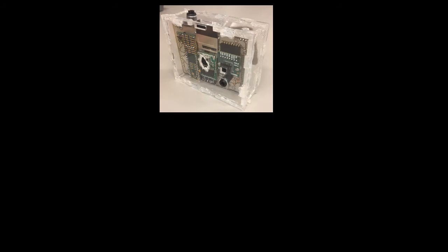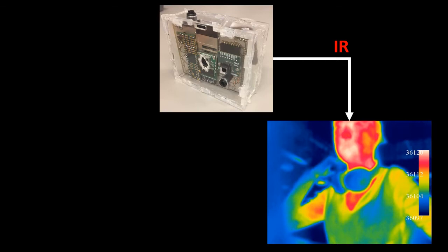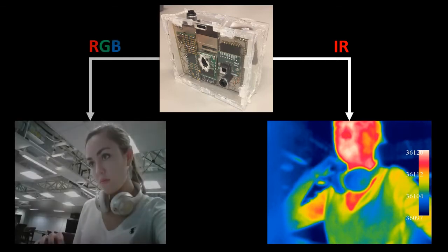This camera, when used in live stream mode, can broadcast infrared video at about 3 to 5 FPS, or frames per second, with a range of about 20 feet. The RGB camera, which can take still color images with up to 5 megapixel resolution, is a bonus feature which can be activated with the push of a button, which saves the image files to an onboard SD card. This subsystem integrates with the Raspberry Pi base output module previously mentioned.